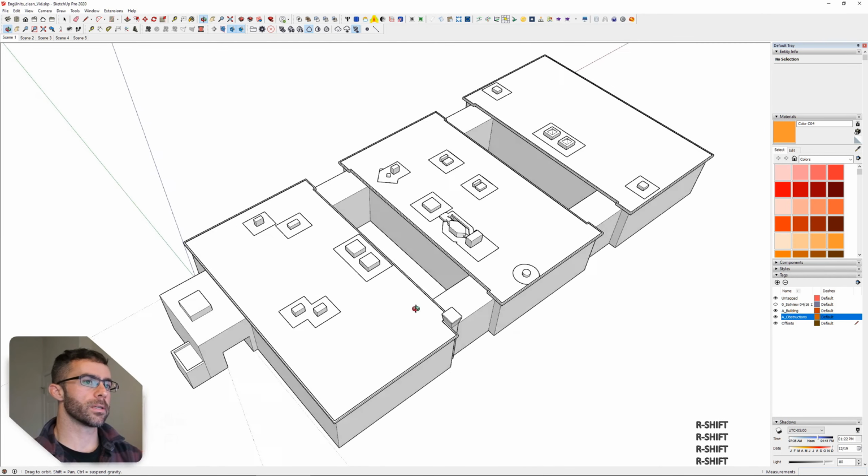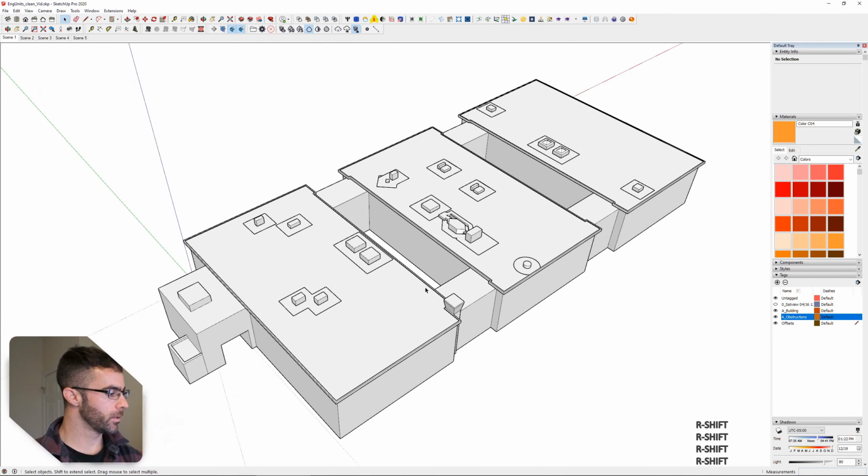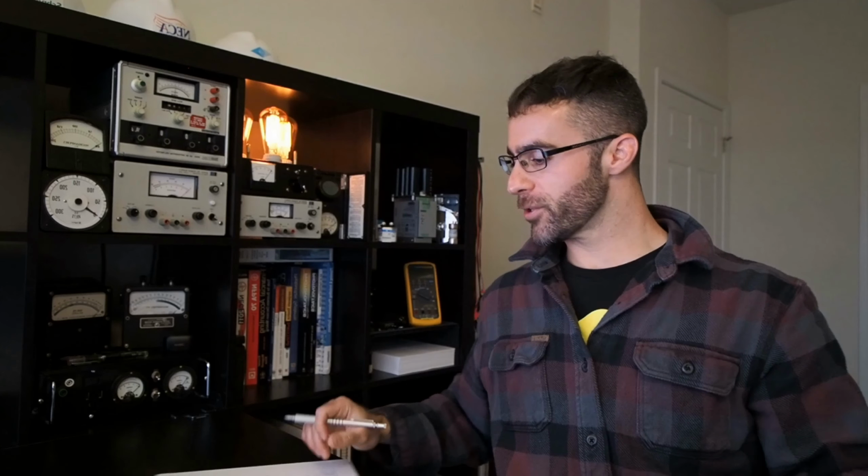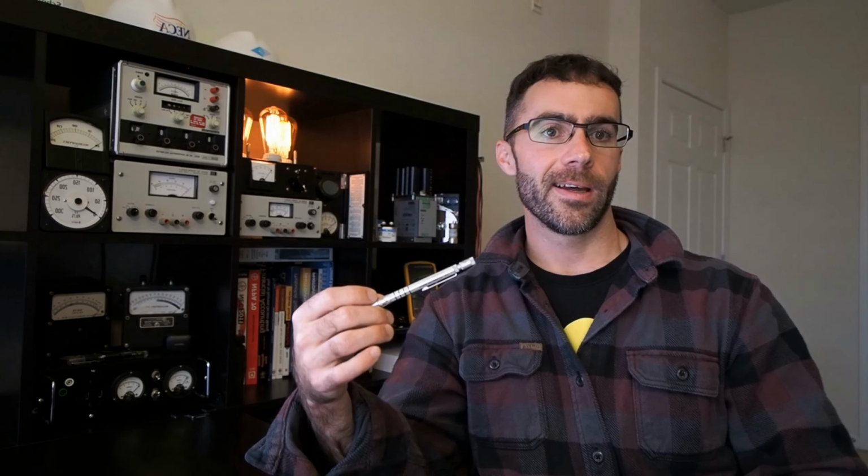One other consideration is the electrical working clearances. So if you had inverters on the roof, if you knew where you were going to be putting those, you'd want to make sure you refreshed your memory from the electrical code. And I have some notes here. Section 110.26(A)(1) is where you're going to get the working clearances for most electrical equipment on a building.